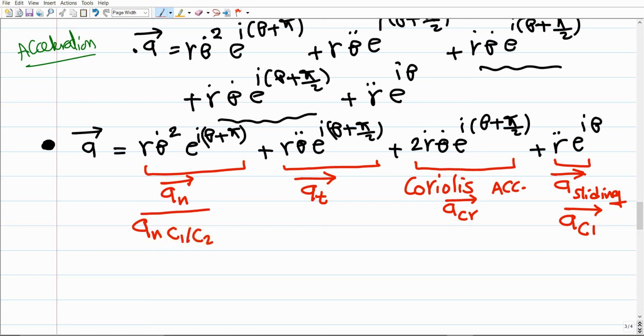So it should be a relative acceleration that basically depends on the rotation of the link. That's why we already have theta dot, which defines the rotation of the link, right? But this term has no theta dot or theta double dot. So this term of the acceleration does not depend on the rotation of the link. For sure, there is an effect, definitely. But originally, this one just describes the sliding motion over the link, assuming that the link is fixed, not rotating.